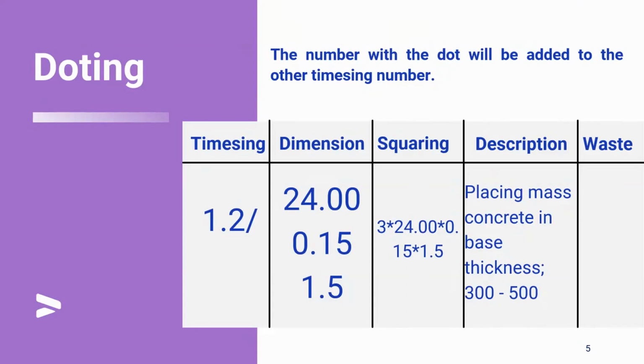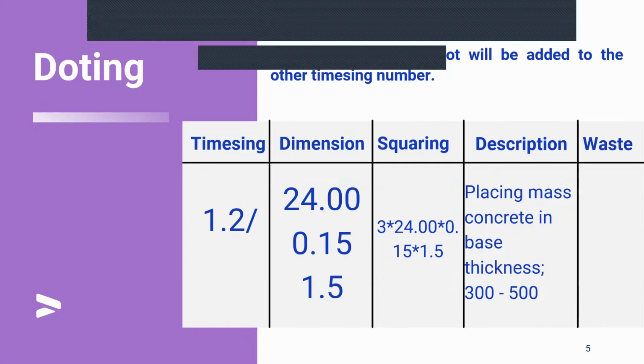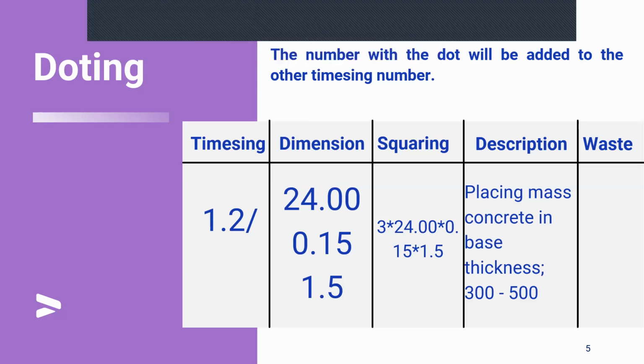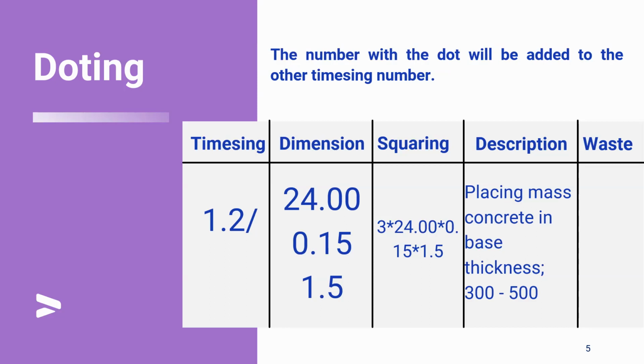my client needs to know that I spent a certain amount of money. Even if I'm taking the money from my hand, I need to show it on my Excel sheet or whatever my client is going to see. So now I have calculated for just 2 units of that particular dimension. How do I add the 1 unit extra that I'm bringing on board? How you add it is 1 dot. That is the essence of dots. Dotting is 1.2. So 1.2 is as good as 3. So you won't be multiplying your total dimension by 2 again. You'll be multiplying it by 3.